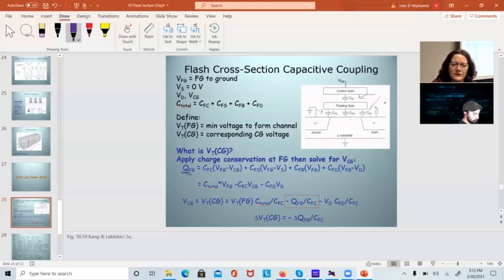My total of the CVs are this floating gate capacitance times the voltage across it, the floating gate voltage minus the control gate voltage, et cetera, et cetera, et cetera. And I go through and I write all those separate charges down. And then we define the total voltage has to equal the rest of this.